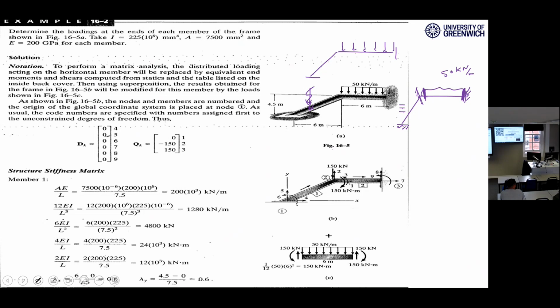It means that these left fixed moments are some sort of external loads applying on this point. Whatever I was tolerating here, it's like I'm a support. I had some support reactions. When I'm not there, those support reactions are applied on this structure. Right? It means that this is really identical to a structure without that distributed load, but with some fixed moment external forces on this point, plus some reactions here. These reactions, just forget about them, they are here as some reactions for this support.